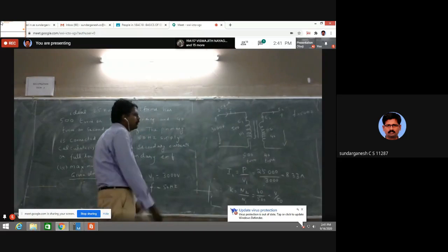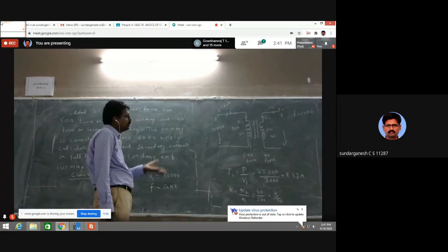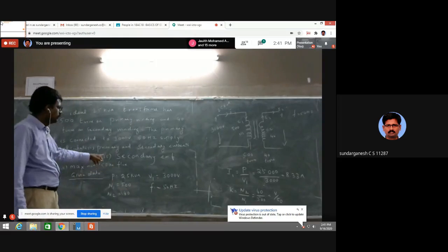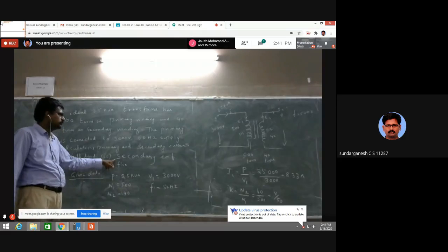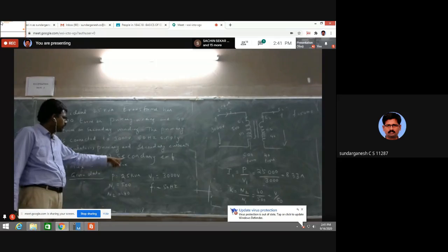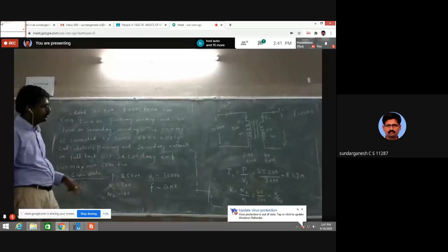From this ratio, I have to find V2. K equal to V2 by V1. I know K, so from this I can find V2. After finding V2, I can find I2. V2 is the secondary EMF. So from this I find K, after that I find V2, so I find the EMF also. Next I find the secondary current also. The maximum core flux is different.